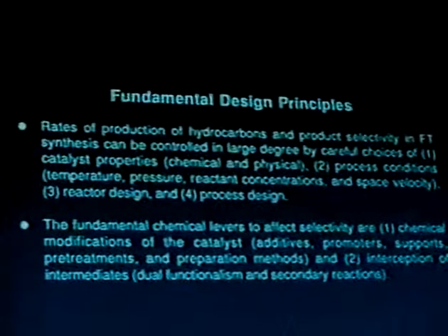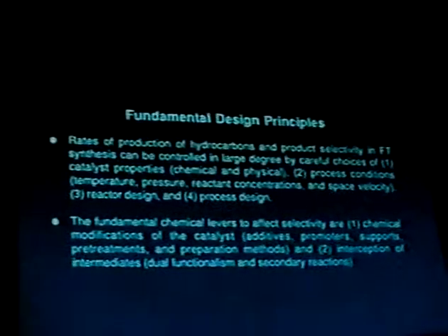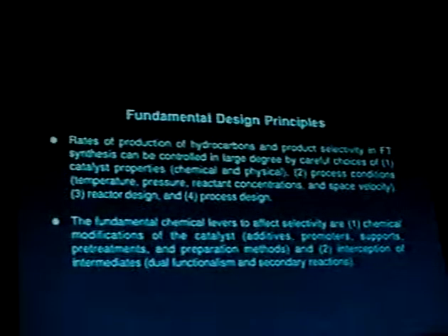Fortunately, now there are some fundamental design principles that can be used to operate within these constraints of Anderson-Schulz-Flory to get at the desired products. The first of these principles is that the rates of production of hydrocarbons and product selectivity in Fischer-Tropsch synthesis can be controlled in large part by careful choices of, first, catalyst properties, second, process conditions such as temperature, pressure, reactant concentrations, and third, reactor design, and fourth, process design.